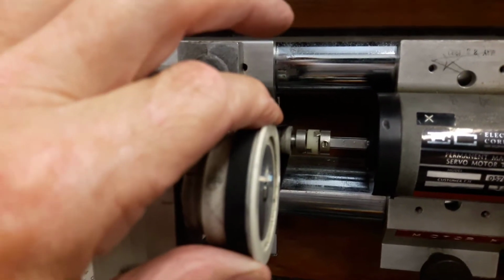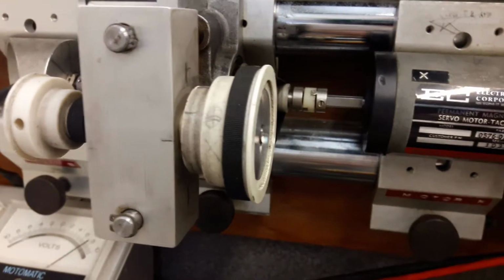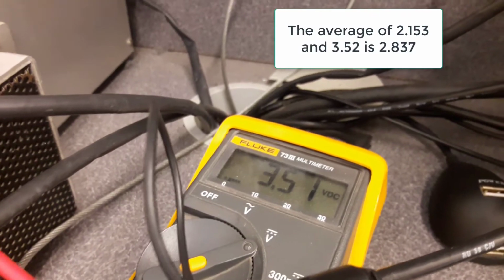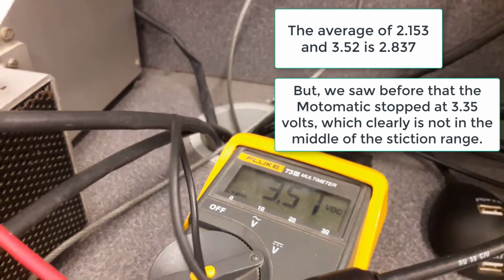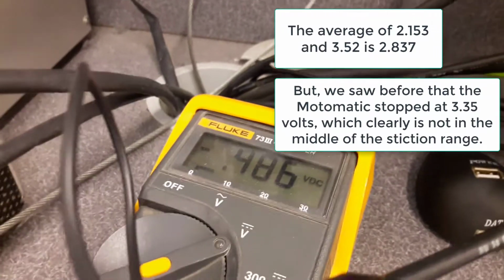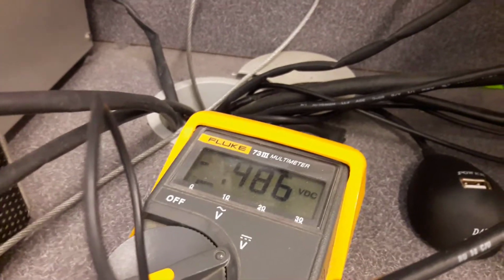Then we want to find the other end of that range. So we turn it in the other direction until we start getting some resistance back. Now I'm at the other end of the range, and I'm at 3.52 volts. What that means is that the center of that stiction range is the average of those two values. You can do a little calculation and find that, and that's where it would wind up if there were no stiction. Now we turn it off, and we spring back to another position. Here in my voltage I have negative 0.486, but I don't know whether that's actually the center of the range.